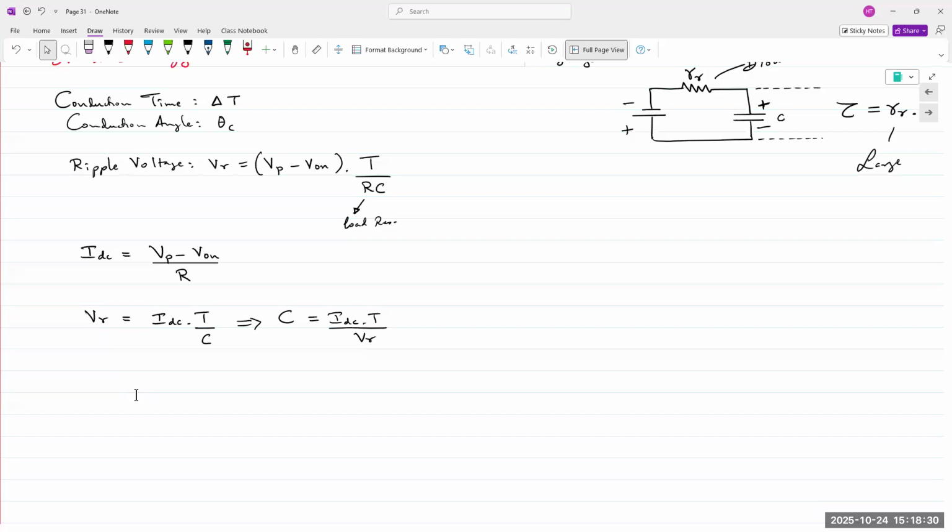So now let's think about if you have a ripple voltage, even a 1 volt ripple, large enough. You have a 6 volt signal with a 1 volt ripple, and you only need 5 volts at the output. So you stick a 5 volt Zener at the output. No matter what the input signal is, it could go from 6 volts to 7 volts with ripple voltage, but your output will be held constant at 5 volts.